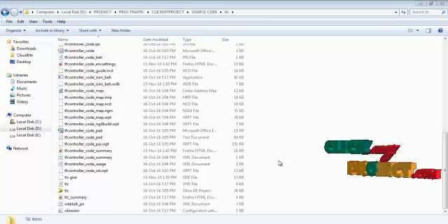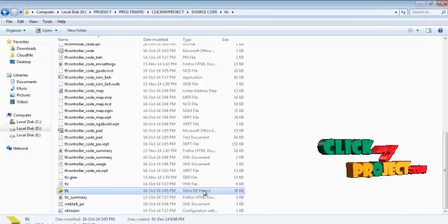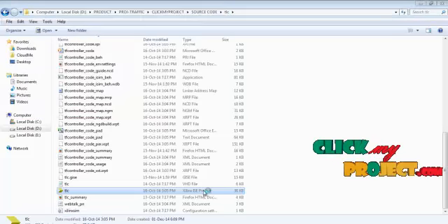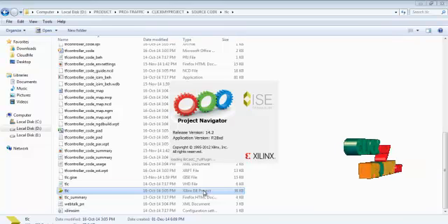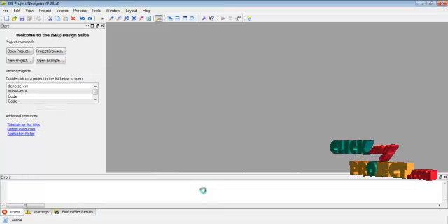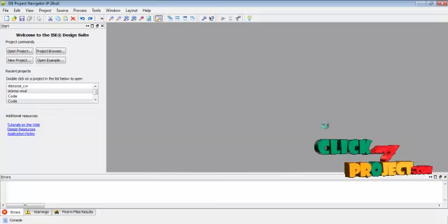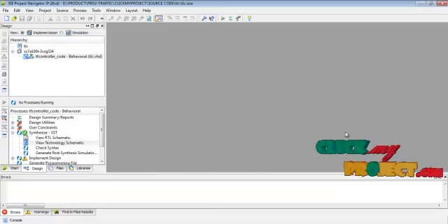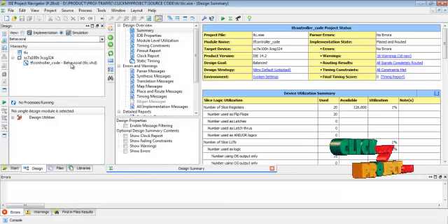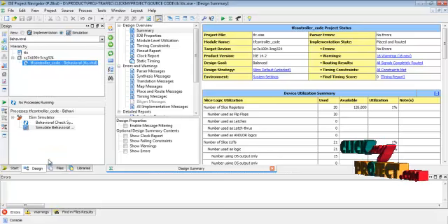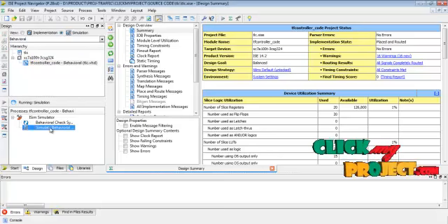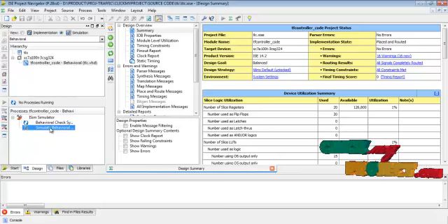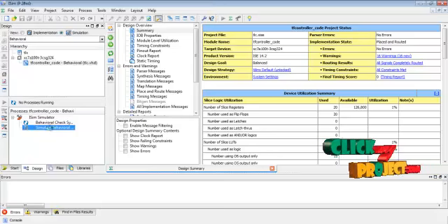And finally we see the output for the product. First we run the traffic light controller ISE project. Our traffic light controller architecture was developed in the VHDL language, using the behavioral modeling process to design our overall architecture. Then we select the simulation and select the traffic light controller code, then run the simulate behavioral model. Then the ISim project navigator is created. This project navigator is mainly used to simulate our process.